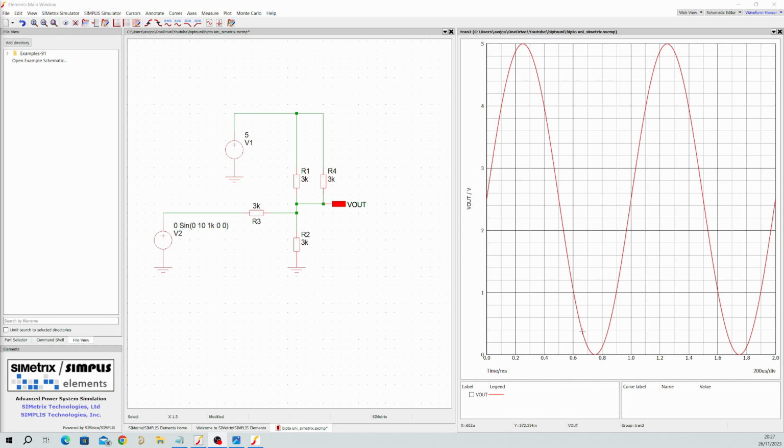The other thing as well, like I said, putting them on the same side of the card gives you a lot of freedom going through your tolerance calculations, such as thermal drift, life, etc. Because thermally, they'll all be seeing the same temperature, so they'll all drift at the same point at the same time. So that's just a bit of a pro tip, really. A lot of people dismiss this and just place things all over the place, but try and keep them together local on the same side of the board, and you can get a much better tolerance out of some not so high price parts like an array of network, for instance.